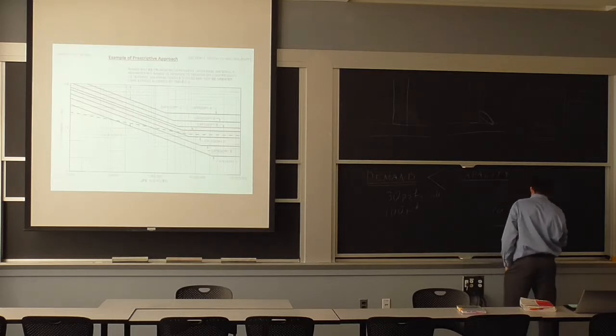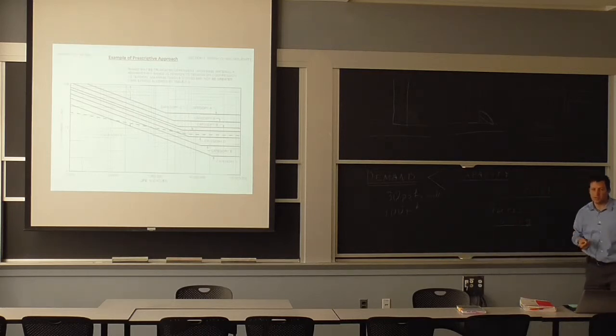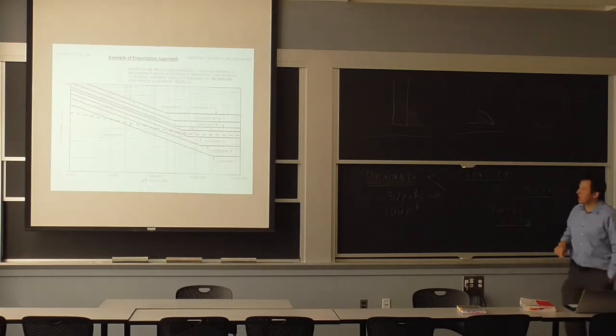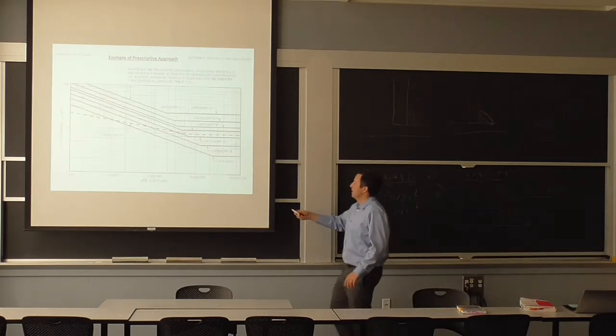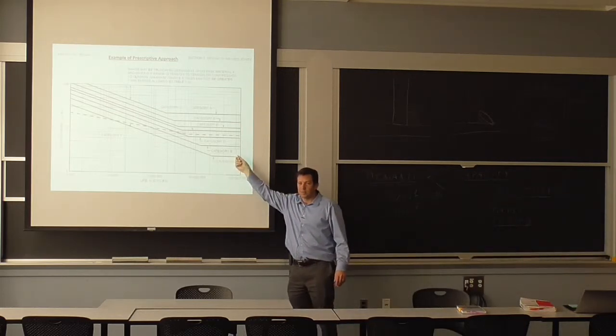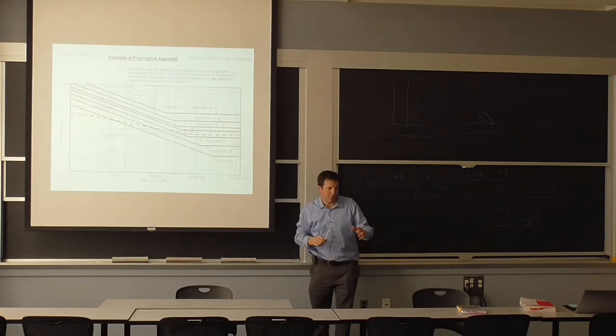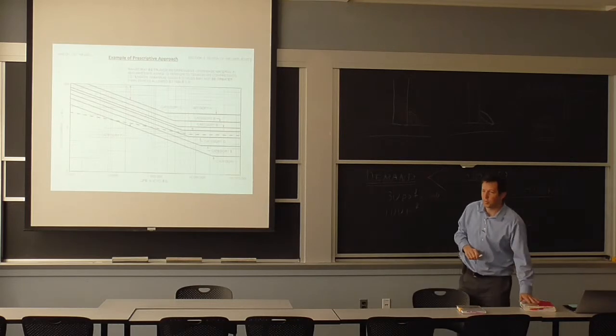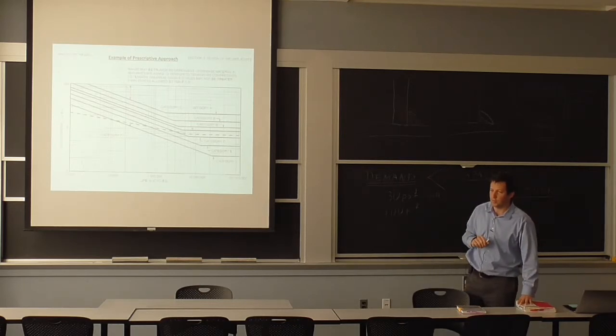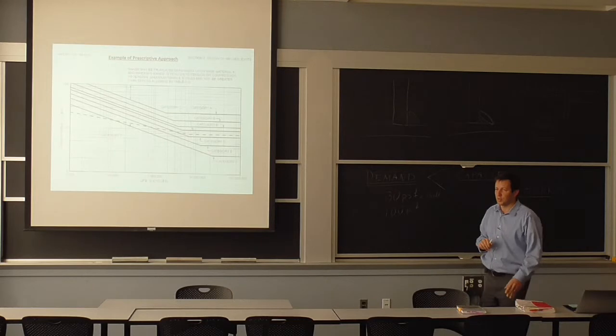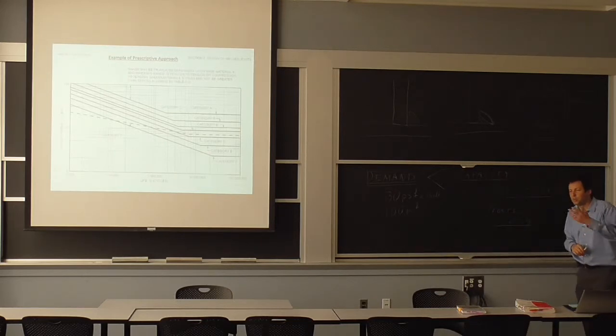It doesn't matter if you're going to take a very, very sophisticated steel alloy or aluminum alloy, if you go into welding, most of these properties, according to the code, any structural steel is the same strength in fatigue, regardless of what you started from. If it qualifies to be welded per this code, this is the chart they give you for all steel. So if you start really strong, but you become more brittle in the welding, therefore they only give you the same allowable.